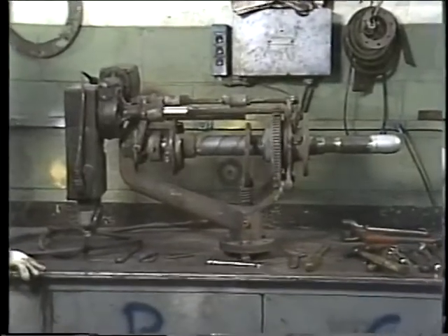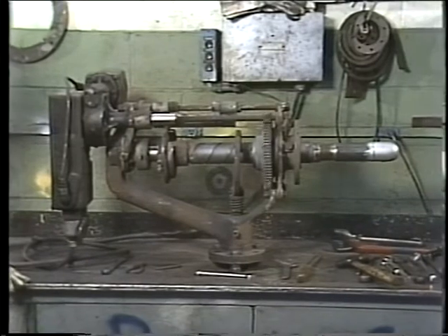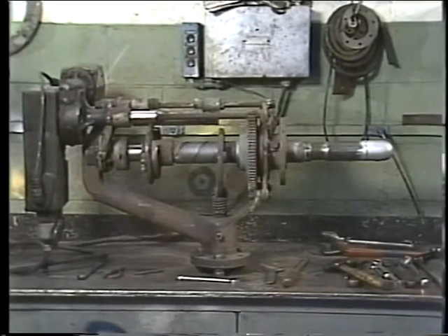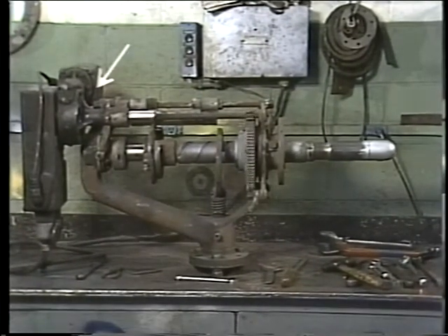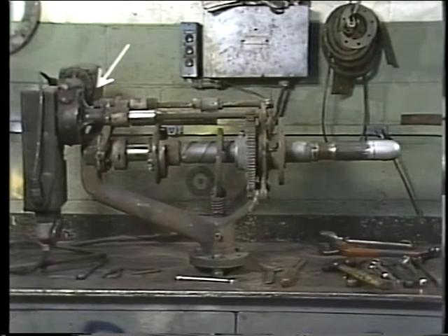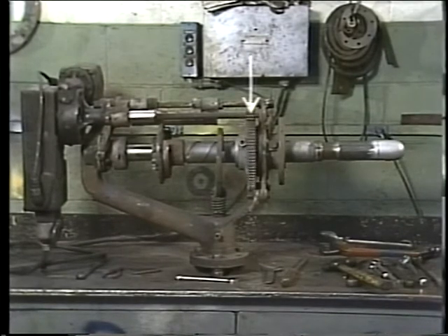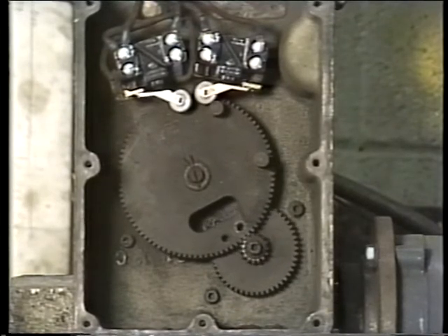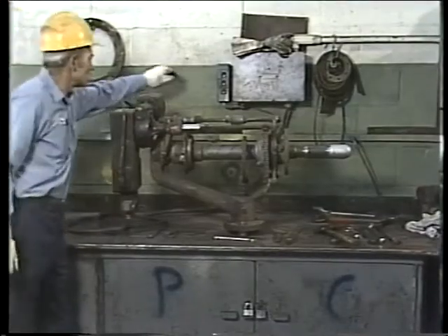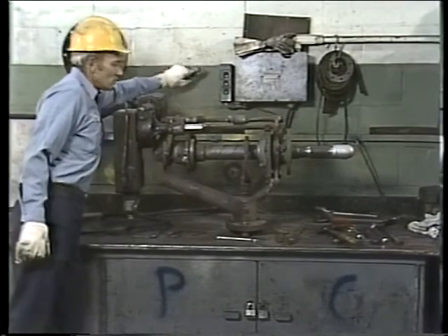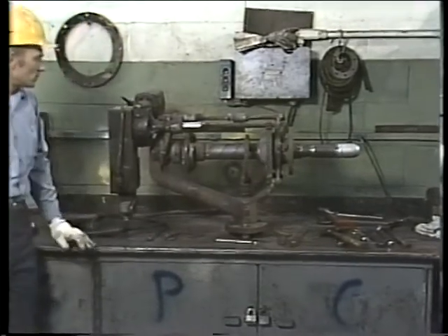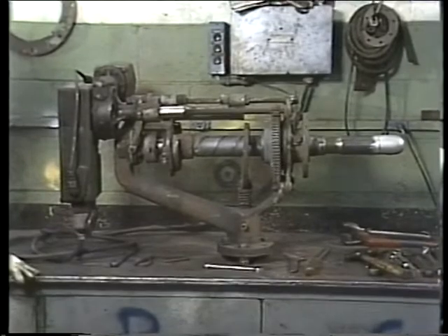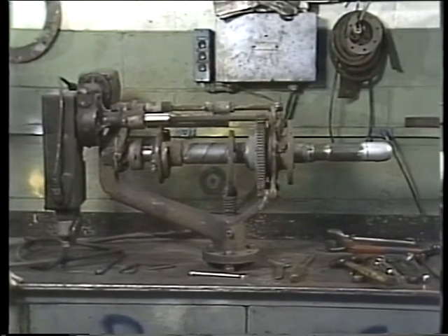This is a typical short tube soot blower set up for a bench test. It's driven by an electric motor which drives through a reduction gearbox. The shaft goes to the main drive gear. Limit switches in the control box control the cycle of the soot blower. At the start of the cycle, the motor is switched on either manually, as it's done in this bench test, or automatically through the boiler's soot blower control system.